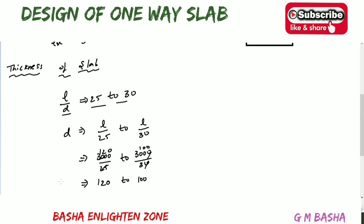You can select the effective depth as 100, 120, or an average like 110 or 115, whatever value within this range. But here I am selecting the effective depth as 120. So you can select whatever in the range you want. That is your effective depth.